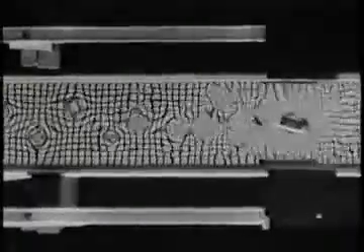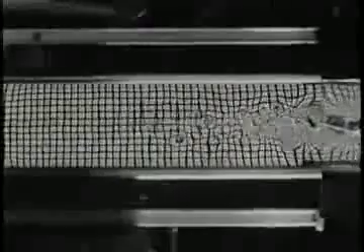Here, we're outside the field, and now the blade enters the field, which is stronger than before. The J cross B forces never let the vortices get started. They reappear as soon as the blade leaves the field. We've now seen rotational J cross B forces creating vorticity and suppressing it.